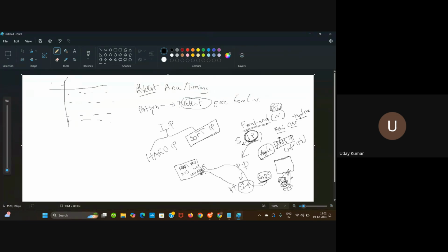You check what the architecture is, what the bus width is, what the frequency of it is, what type of bus they are using, and what the throughput of your architecture is. You will be checking, and based on that, once you get this soft DSP, you will be customizing this DSP so that it will fit into your architecture.